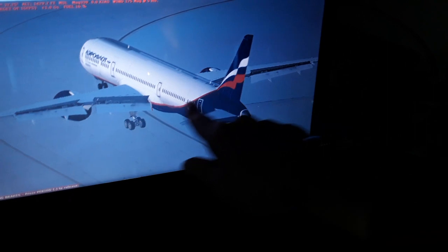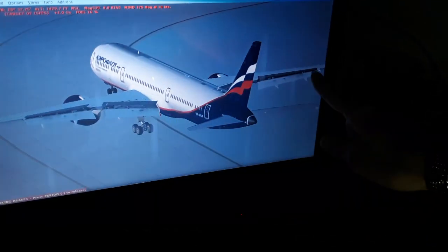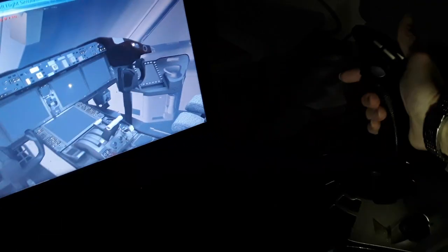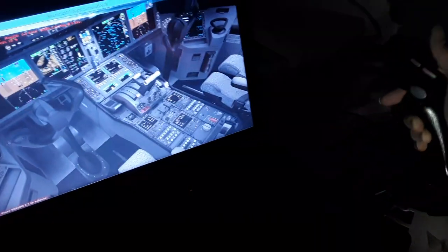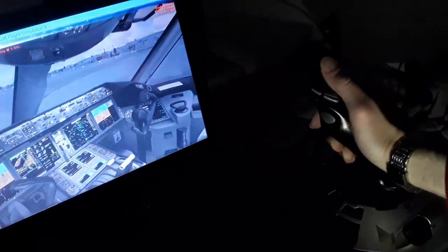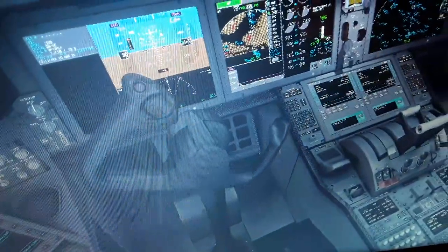The Boeing is also a fly-by-wire aircraft. It has flight control computers to control the input, like in the Airbus aircraft. So you can see the spoilers now fully extended, also the flaps, the ailerons here, left and right ailerons, and the flaperons here, left and right. So we have all flight controls together like this, interconnected. You can see this is the control wheel, make left and right turns like this. Ailerons and spoilers in the Airbus joystick and ailerons and spoilers in the Boeing. You use the control wheel of the yoke like this, very easy, very simple.